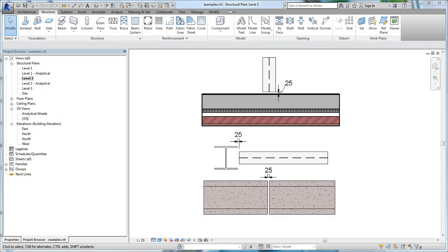Cutback defines the space between the end of a beam and the element to which it is joined. Steel beams and precast beams cut back at a join depending on several default properties. In this video, we will explore how cutback works by default and how you can specify a geometry reference from which the beam will cut back.